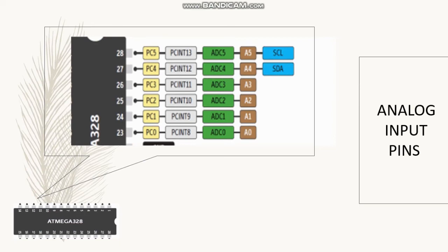For a particular pin, we can source 20 milliampere of current for DC, and at a typical 3.0 volt a pin can output 50 milliampere of current. The clock speed can range from a minimum of 4 megahertz, or we can even start with 1 megahertz, up to about 16 megahertz. It also has an internal oscillator, so which one of them is used depends entirely on how we program the fuses of the microcontroller.